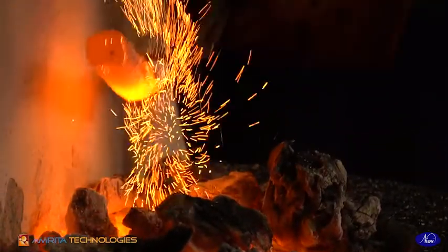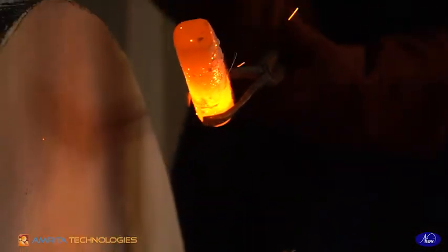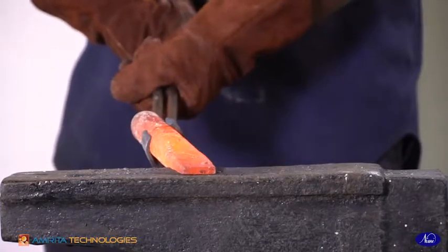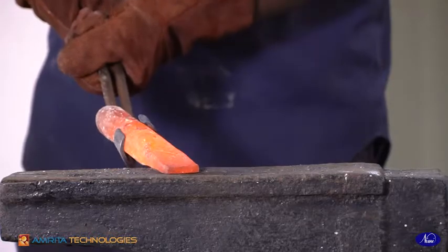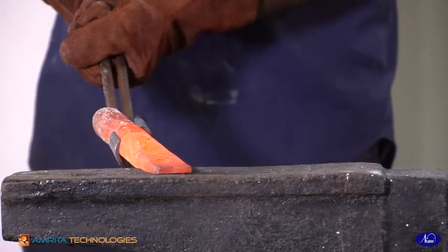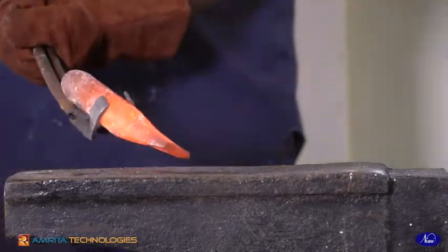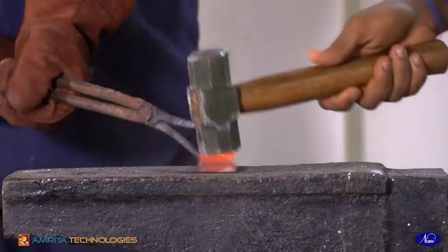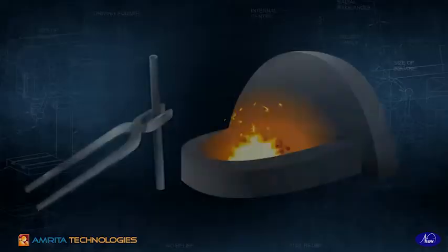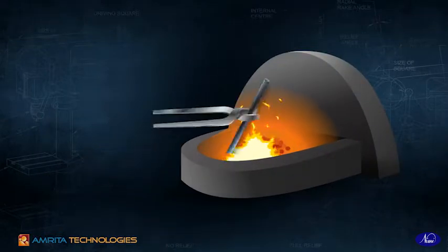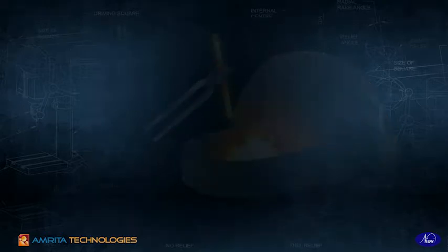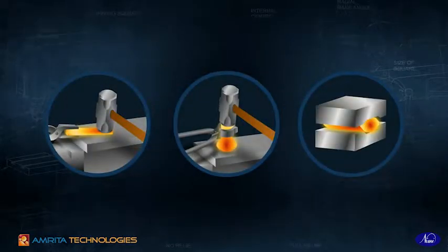Forging is a manufacturing process which involves heating metals to the plastic stage and then shaping those metals using localized compressive forces. Blows are delivered using a suitable die and hammer until the metal's final shape is obtained. There are many different kinds of forging processes. However, they can be grouped into three main classes.